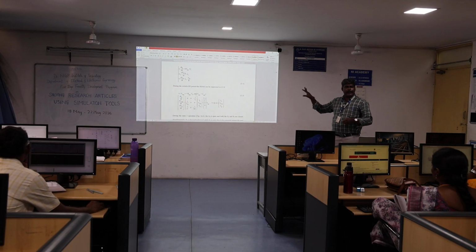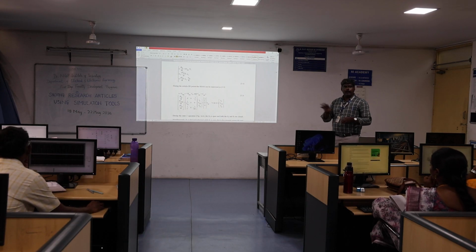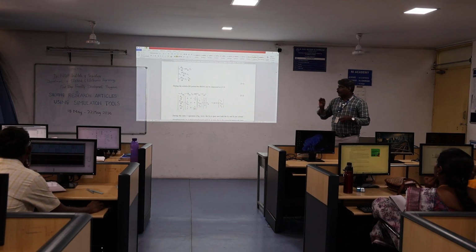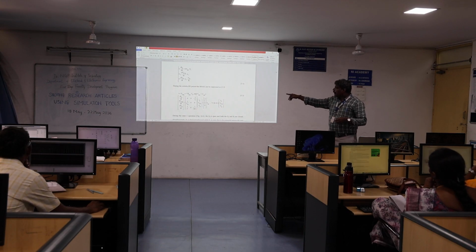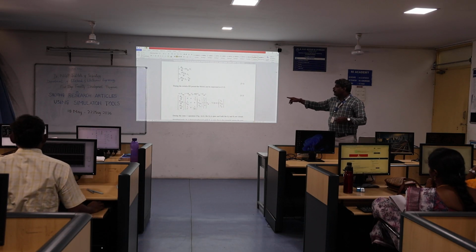System means your converter is based on how many storage elements are available in your converter. Storage elements mean inductor and capacitor. For the given circuit, you have three storage elements, two capacitors and one inductor. For a capacitor, we express voltage as the state variable. For the inductor, we represent current as the state variable. So now start with dIL divided by dt, dVCB divided by dt, and dV naught divided by